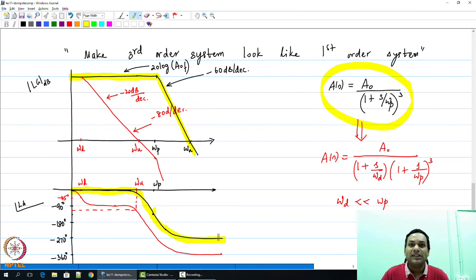Now what can we say about the stability of this system? Clearly, as I have drawn it, the system has a gain, which I'm going to show in maybe light blue, that is larger than 1 when the phase hits minus 180 degrees. So clearly, when the phase hits 180 degrees, the system has a gain which is much larger than 1. And of course, the system has a strong potential for instability.